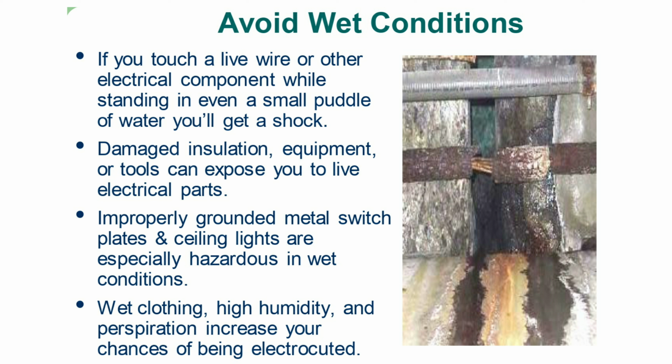Avoid wet conditions. If you touch a live wire or other electrical component while standing in even a small puddle of water, you'll get a shock. Damaged insulation, equipment, or tools can expose you to live electrical parts. Improperly grounded metal switch plates and ceiling lights are especially hazardous in wet conditions. Wet clothing, high humidity, and perspiration increase your chances of being electrocuted.